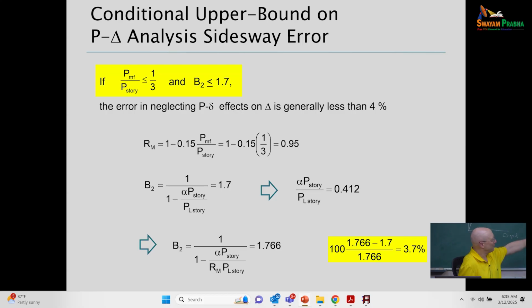He may have a conservative estimate with this way of applying B1, but so be it. For most steel building frames, the B1 factor is often 1 anyway, and is not much larger than 1 in most situations.